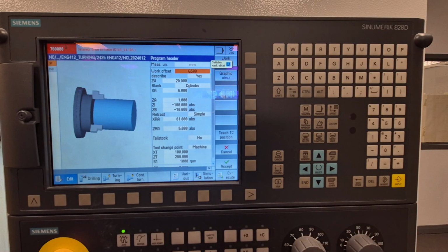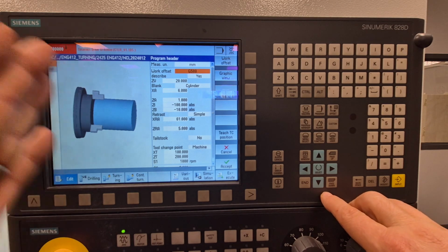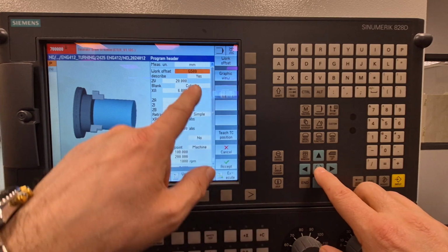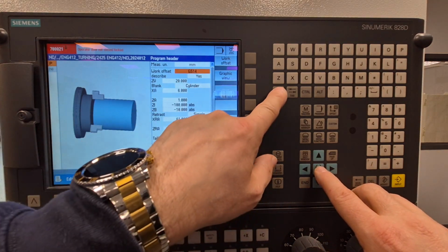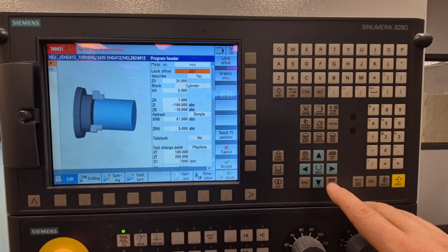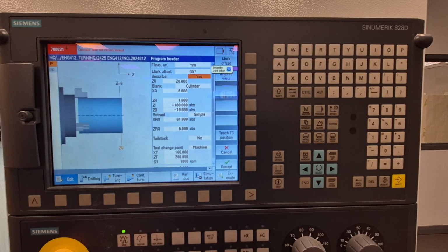This is workpiece reference. Whereabouts is the front face, because we work from 0 to minus. If you're going to do a 10 mil depth hole, this is where it's going to come from. So I press select. I can select any number I want. If I press shift, I can do that number in reverse. I want 57 on that one there. This one, when you use the down arrow key again, it goes to yes.